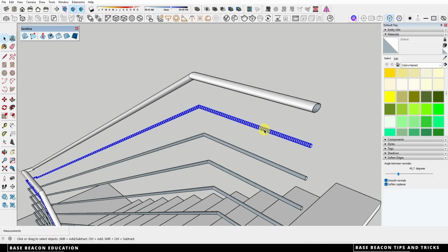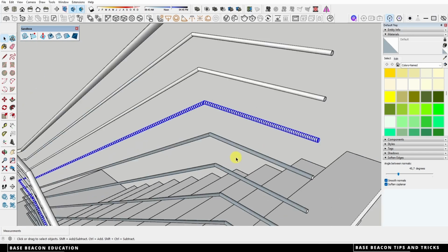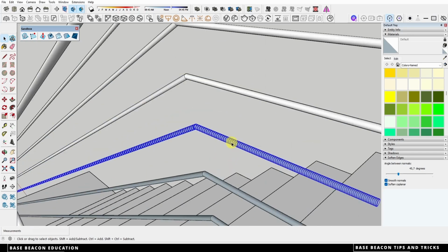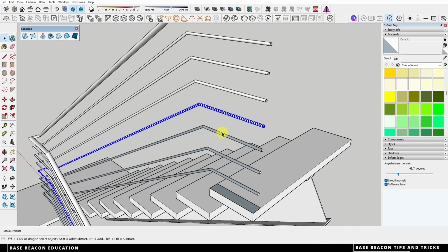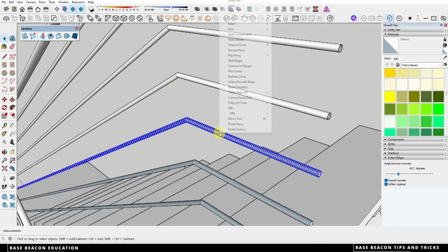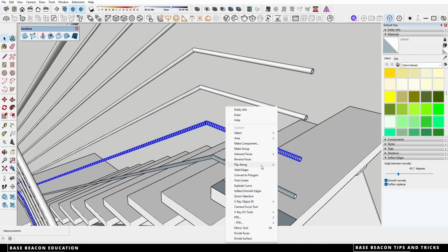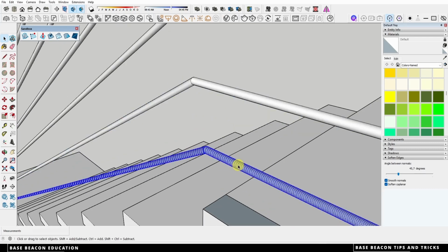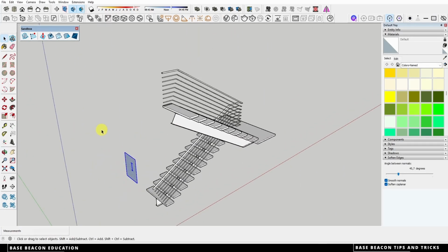Same thing there. Same thing there. Again. And the reason why I do this is because when you start rendering or applying materials, if you have your faces facing the wrong way, it could affect how the renders look. So that's why I like my faces reversed to show the white on the exterior side. And there we go. And we can delete that.